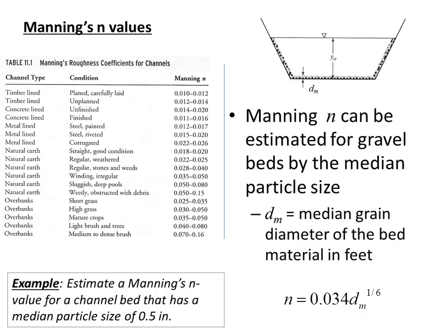And if we substitute that into the Strickler equation, then this term is 0.589. So the N value is 0.020. Okay, so that would be for a relatively standard half-inch diameter circular stone particle.